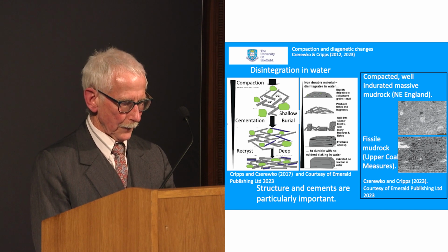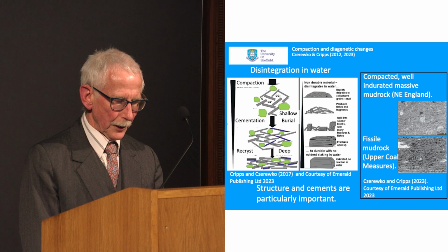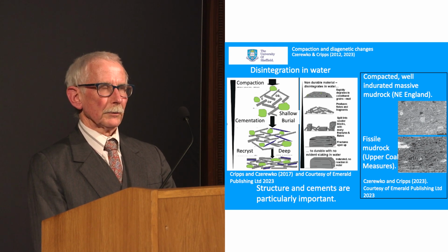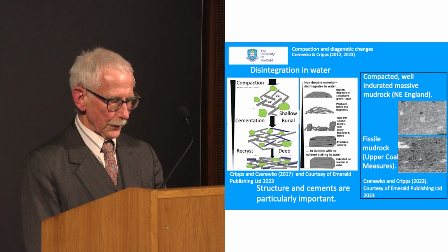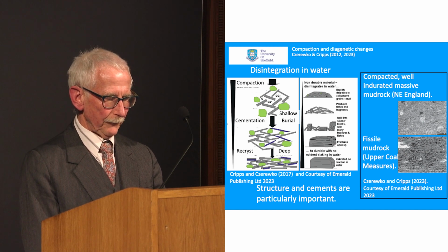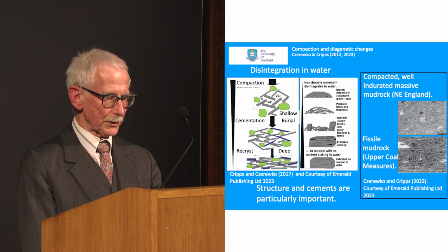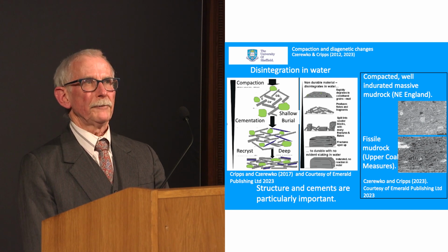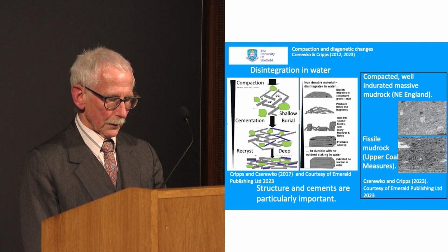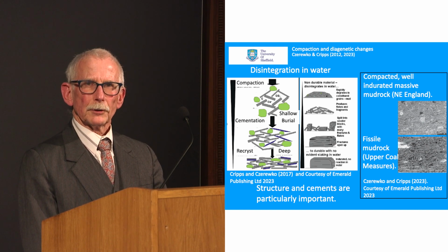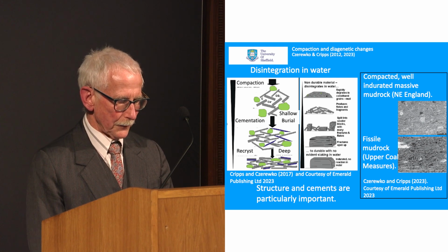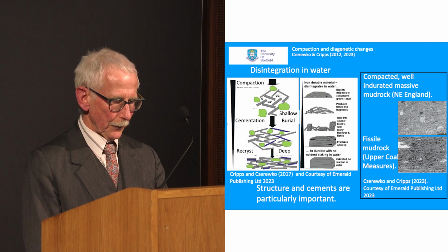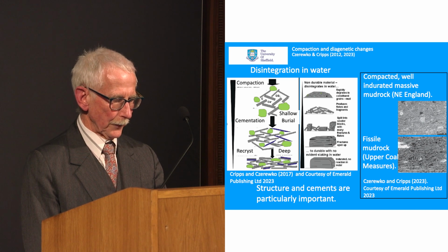Apart from the clay mineral alignment, the silt particles, the mainly quartz and feldspar particles within the material, may also be flattened by distortion and enlargement in their size, which will occur preferentially by growth in a horizontal direction because of the vertical stress. And this makes them more platy in shape, making the material more anisotropic.